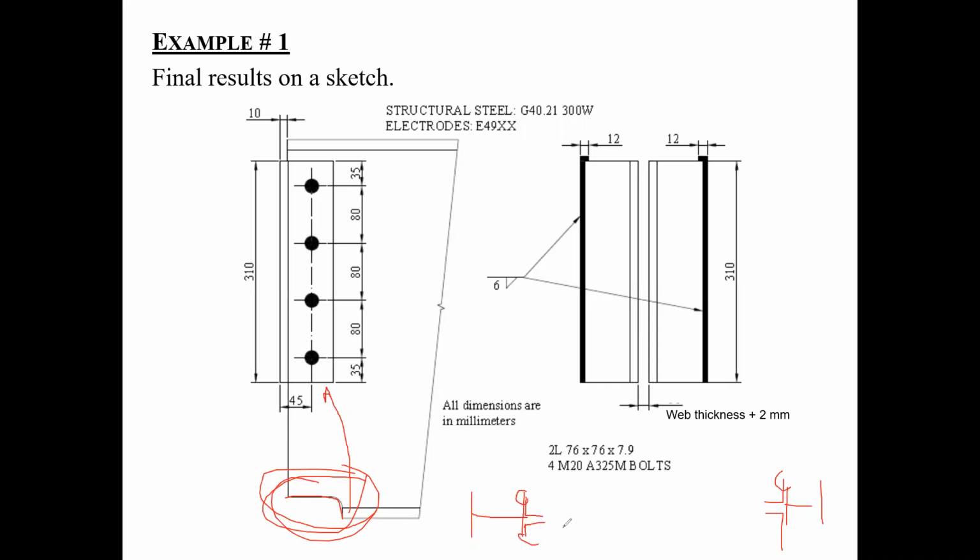And they're going to be fairly straight, the columns. Whatever the dimension is from column to column, you always make the beam on both sides 10 millimeters shorter than what you actually need on the site, and that's to help for erection. So this is called a coped beam, okay?